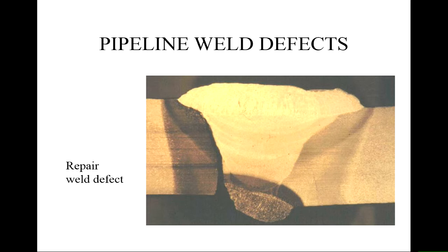Another improper repair, just look at this image and it's very clear to see what happened. As we look at the micrograph on the left hand side, the HAZ is very intense. So because of that, look, the crack propagates all the way in the heat affected zone. Again, another one caused by repairs.